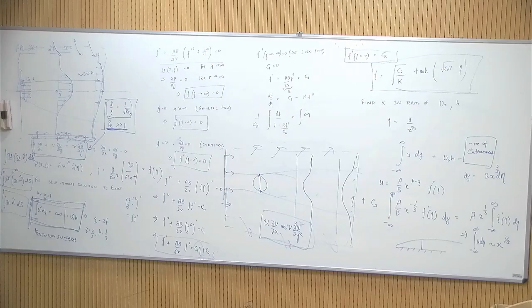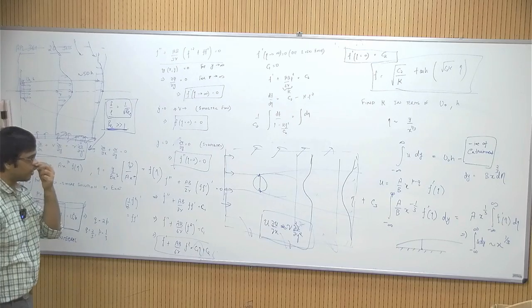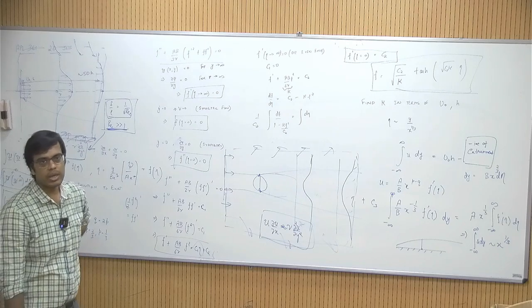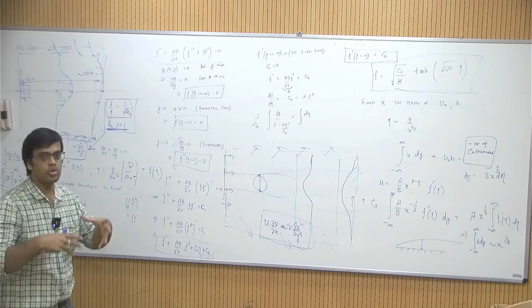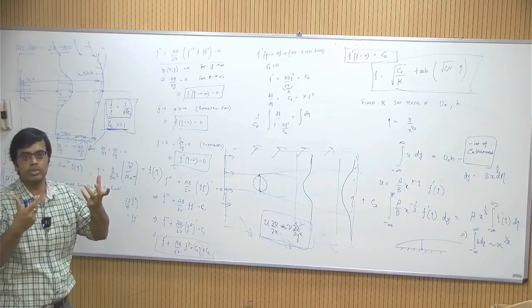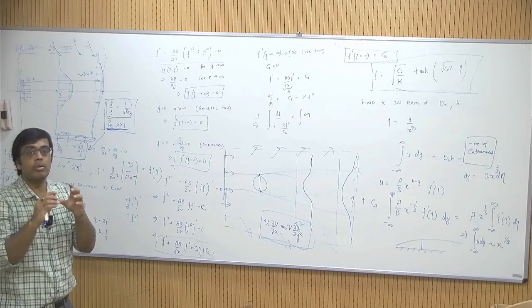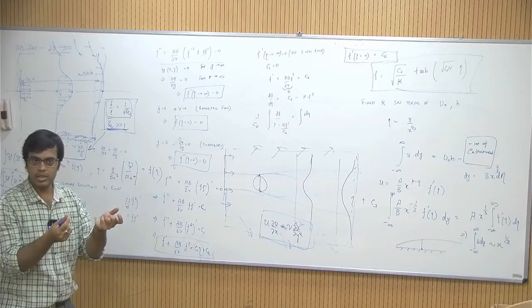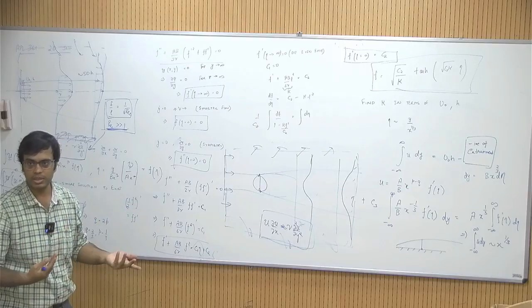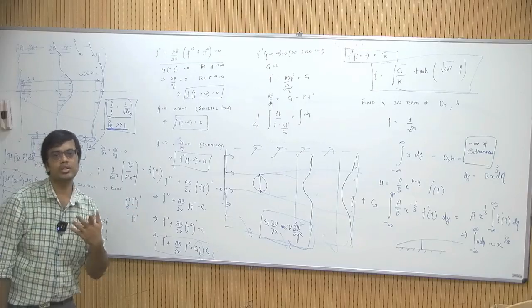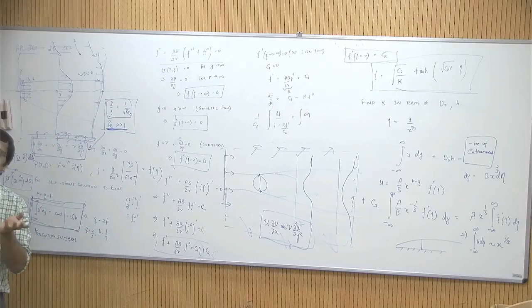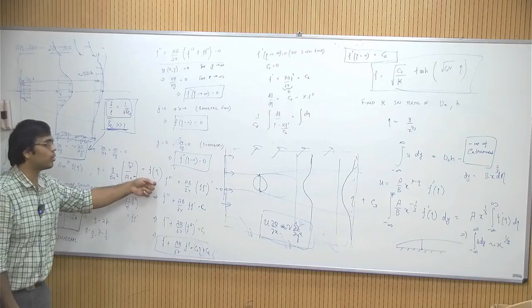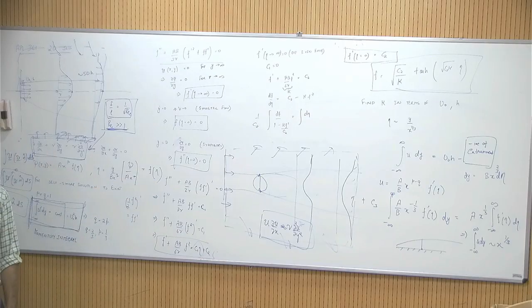Self similarity is very related to the concept of fractals actually, where what you say is, if you zoom out enough, you're looking at the same solution technically. So you are maintaining something which is a combination of your two independent variables as constant. That is why you're getting the same function back. The solution is not a function of two independent coordinates separately, it's a function of their combination, and along that line where eta is constant, you will get the same value of f.